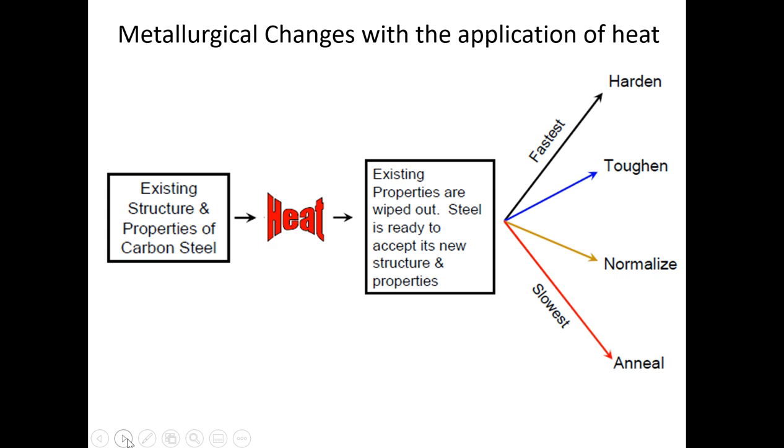However, I do want you to know that if you start seeing cracks around your welds, and you're welding something HSLA, or you're into dual phase materials, or you're doing something that's causing cracks, you have in your capability a way of adding a little bit of extra heat in a post heat while you've got a grip on this part. You could actually put extra pulses in it at the end to literally soften the structure enough that you've annealed it or normalized it or taken a bunch of the critical stresses out of this quenched joint.